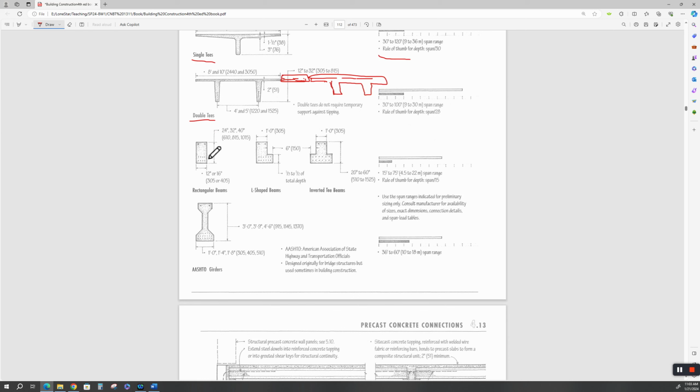Rectangular beams can be pre-stressed, precast, or they can be post-tensioned. I am not a big fan of post-tensioning. There's a lot of things that can go wrong with post-tensioning. Now, there are some benefits to it, and the Post-Tensioning Institute will argue with me on that. Again, if it's a commercial structure and it's well engineered, well inspected, well managed, yes, you can get by with it.